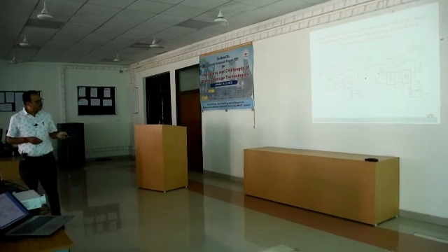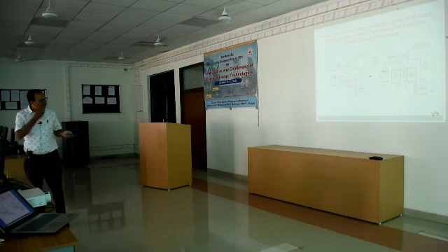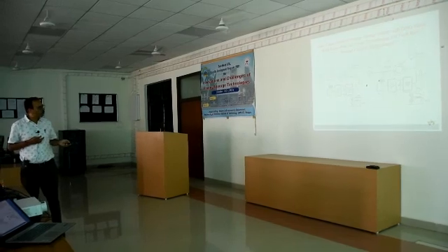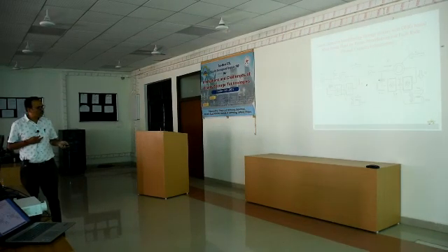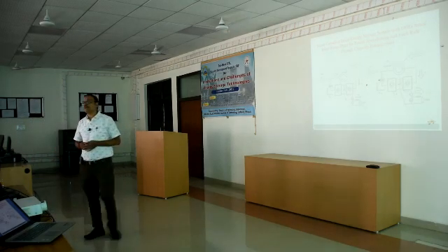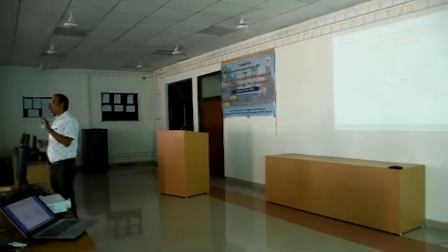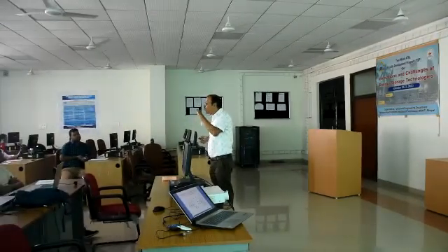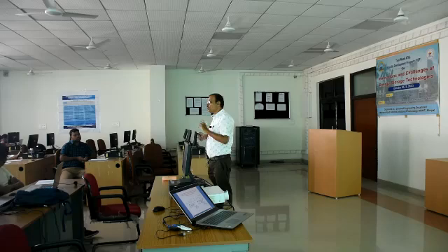And you are receiving the power from the rotor. This can act to store the energy depending upon how much power is generated. If you want to maintain a constant power, this energy storage system will store the energy. If you want to reduce the power, then it will supply the energy. Under the fault conditions, the voltage at the grid will reduce, and at that time it is required to provide large reactive power support to your grid, because the voltage is going to collapse. To maintain the voltage, you have to increase the reactive power injection to the grid.